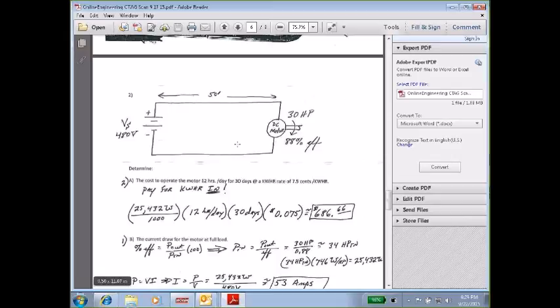You have to pay for what's going in. So we take the power in watts, divide it by 1,000 to put that into kilowatts, times the 12 hours per day, times the 30 days, times 0.075, that would be 7.5 cents per kilowatt hour, and it's $686.66.